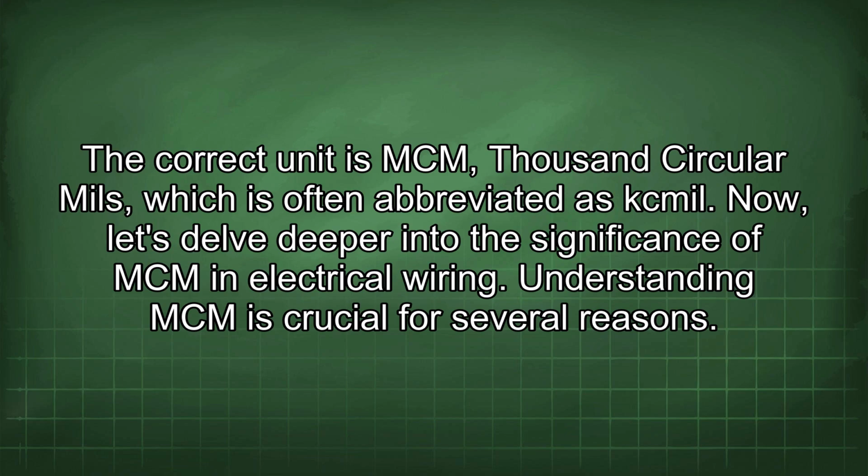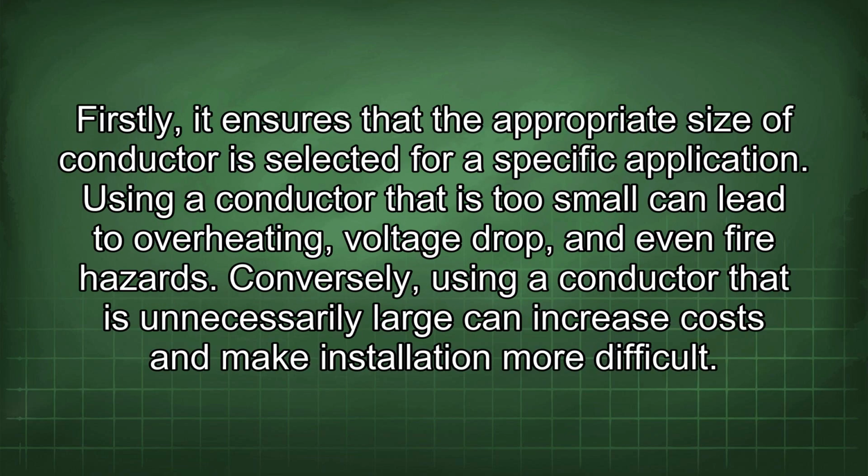Now let's delve deeper into the significance of MCM in electrical wiring. Understanding MCM is crucial for several reasons. Firstly, it ensures that the appropriate size of conductor is selected for a specific application. Using a conductor that is too small can lead to overheating, voltage drop, and even fire hazards. Conversely, using a conductor that is unnecessarily large can increase costs and make installation more difficult.